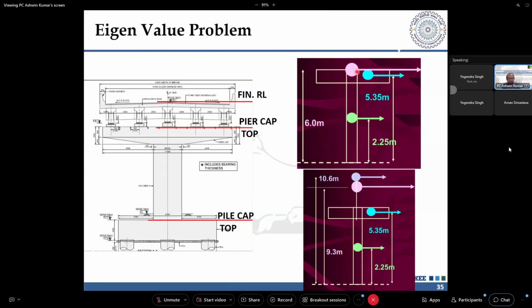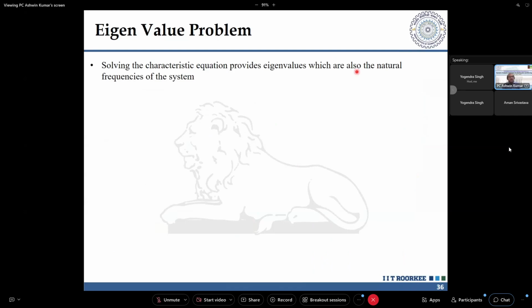Shear, not shear. You don't want shear hinges to form. You want flexural hinges, as flexural hinges give the more ductile response of the pier. So it depends on you on what your purpose is, and then accordingly you need to find out which model is going to work for you, right?